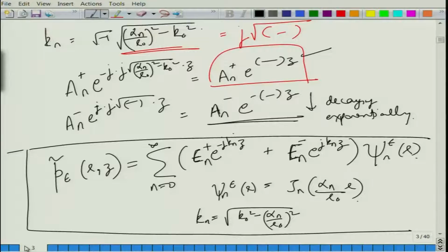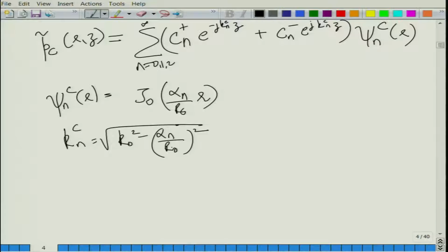So, notice the difference here, actually you can think of this as k n e and k n a. K n e and k n a are pretty much the same, because the radius of the inlet and outlet pipe are same, but in this thing this is r naught. So, r naught is different. Typically for automotive mufflers, the expansion ratio, or the radius ratio, can vary from 3 to something like 6, and so the area ratio can be something like 9 to 36.